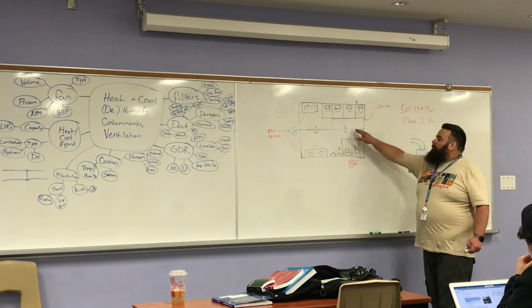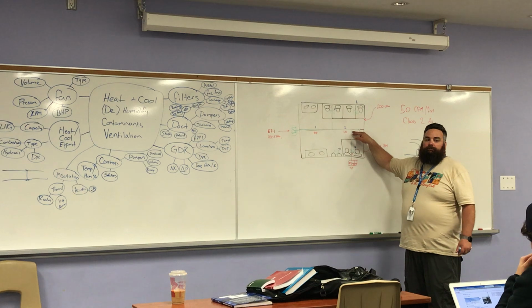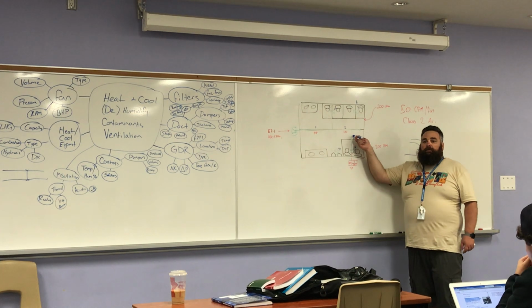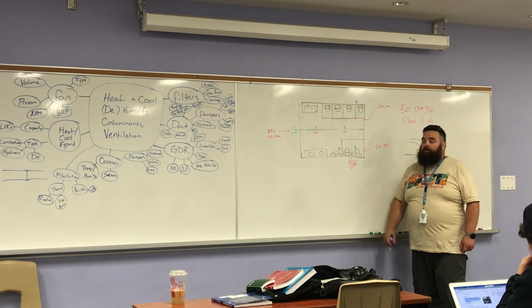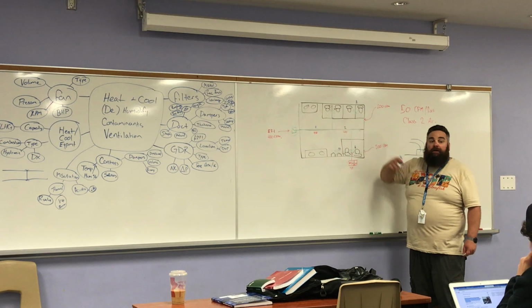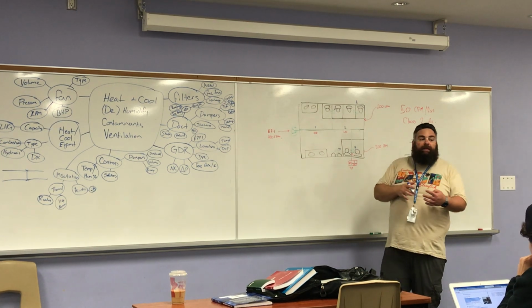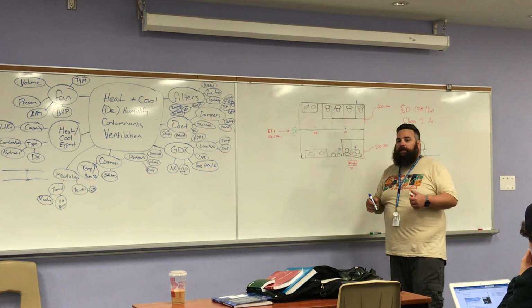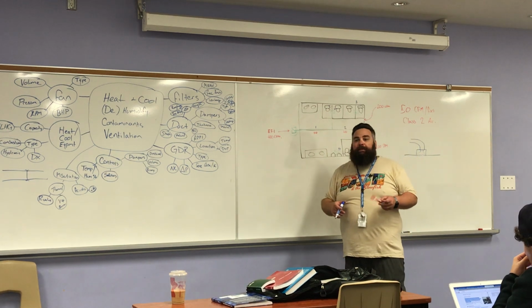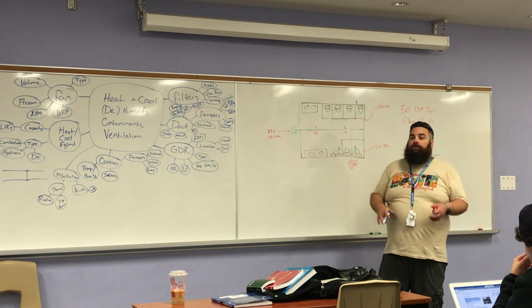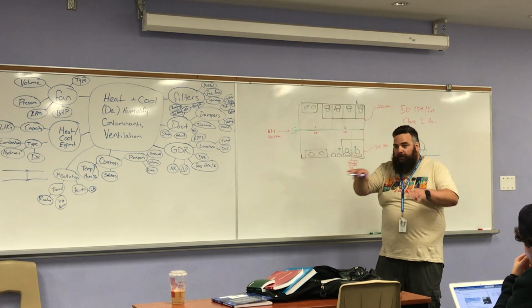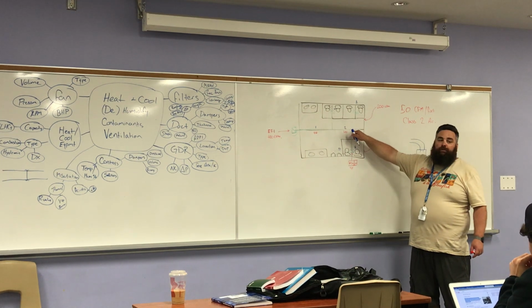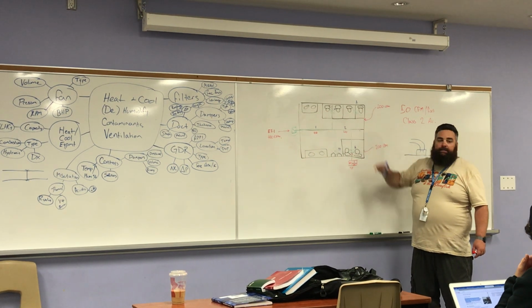What about here? Now what? Direction? I have to turn 90 degrees, right? But am I all by myself? Is it just 100 CFM with nothing else going on? There's already 100 CFM from here. Now I have a converging airstream. That takes energy. Think about merging on the 401. Well, 401's not a good example because everyone's going so slow anyway. Faster highway, where everybody's doing 120. And now people are trying to merge. Cars have to slow to let you in, you have to slow to keep pace, so that takes energy. So we are robbed of energy at the convergence. What next?